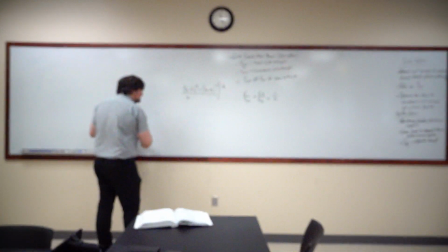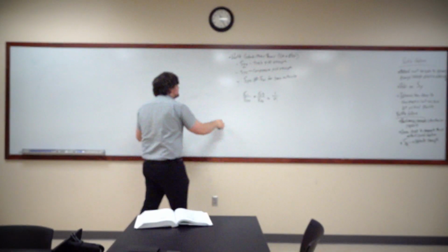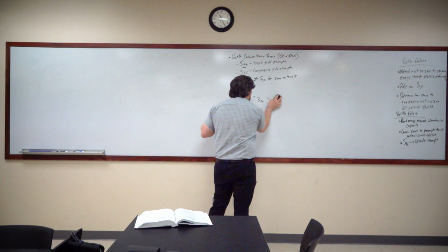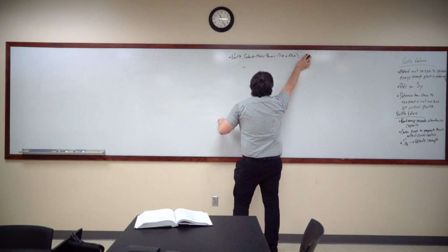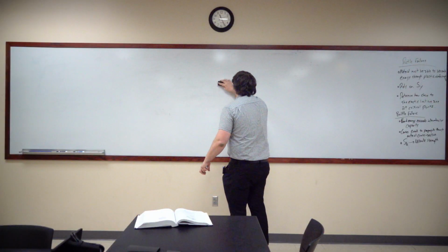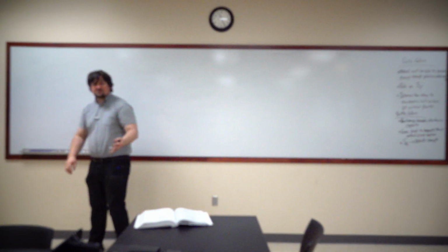This was not uncommon to see inside of the material. And so when the material fails, it was evidence that the material was stretched along the shear directions. But when we're dealing with brittle failure, for brittle materials, even ductile materials that are failing in brittle ways, we're seeing a different kind of stress entirely and a different kind of surface.